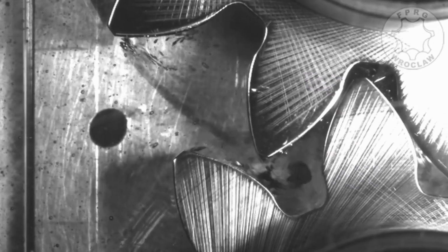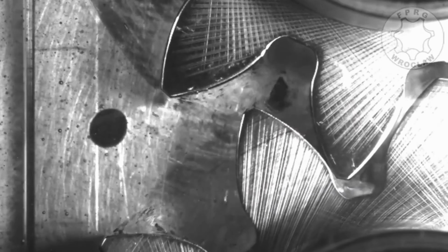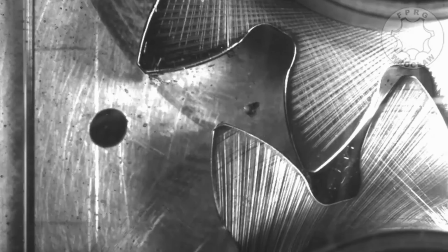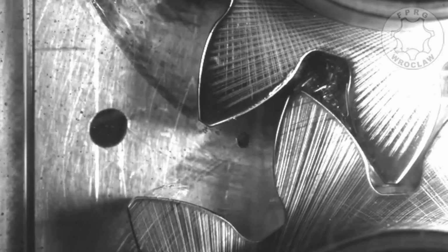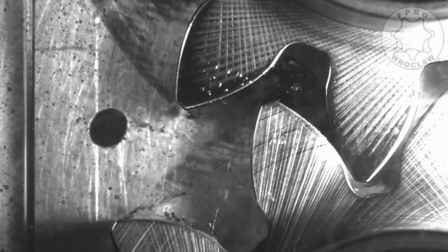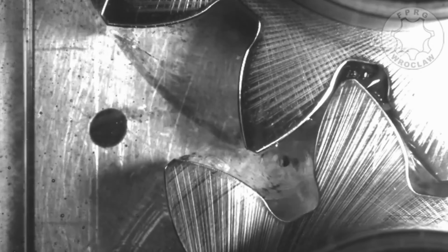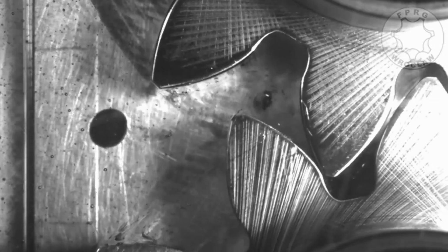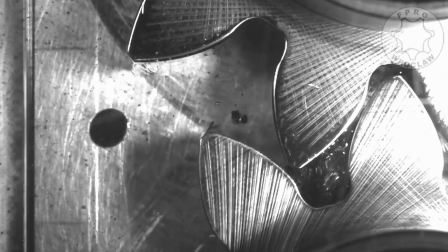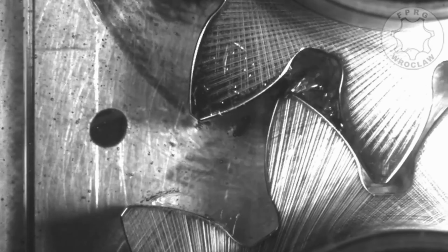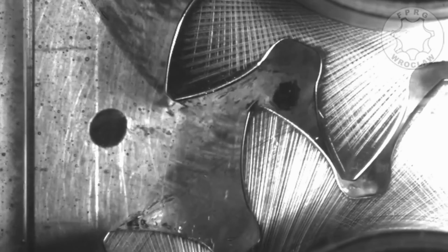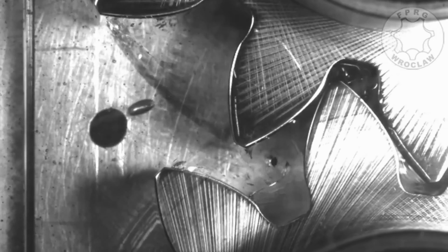True. Here in this short video, we have a great representation of a spur gear pump, and you can see the little vortexes right after the gears unmesh, and that's actually the fluid flashing, and that can cause great cavitation to the pumps. It's quite a unique video. Imagine this pump after 10 hours of this happening. Yeah, there's not going to be much left of your gears after a while.